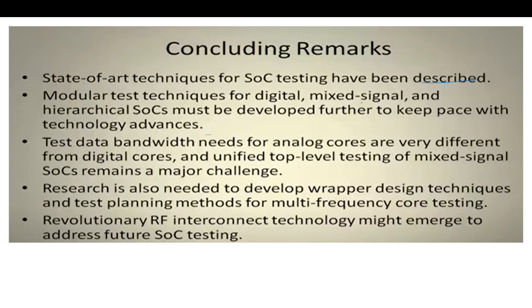Test data bandwidth needs for analog cores are very different from digital cores, and unified top-level testing of mixed signal SOC remains a major challenge. Research is also needed to develop wrapper design techniques and test planning methods for multi-frequency core testing. Revolutionary RF interconnect technology might emerge to address future SOC testing.